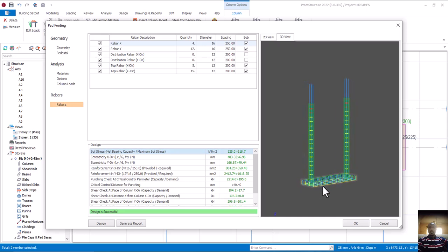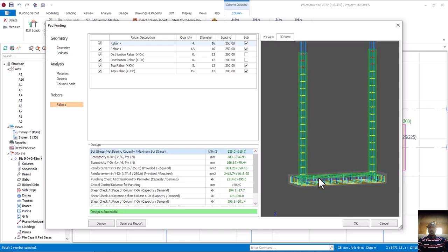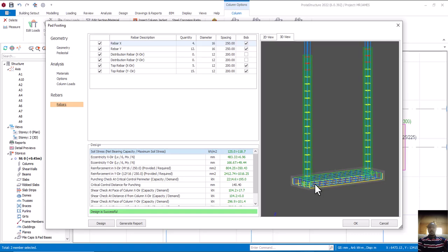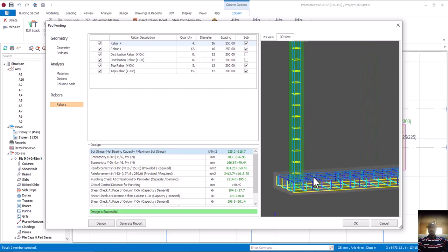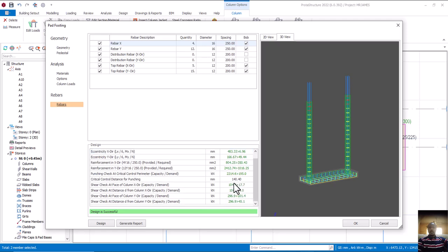And that's why as a structural engineer, if you are at site and you get to a place whereby you're having a combined footing and yet the engineer did not provide the top reinforcement due to an oversight, or maybe he forgot due to detailing, all of that, that is why it's good for you to have the knowledge of design. Automatically, as an engineer at site, you have to provide the top reinforcement for that. Is that okay? All right, that is fine.